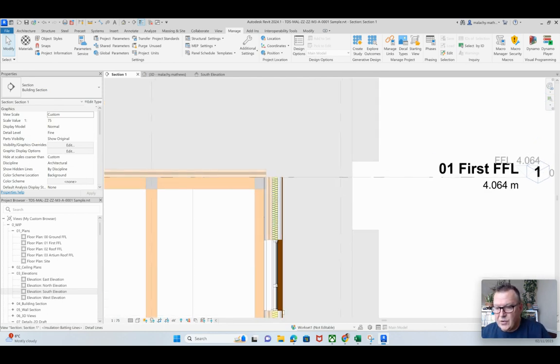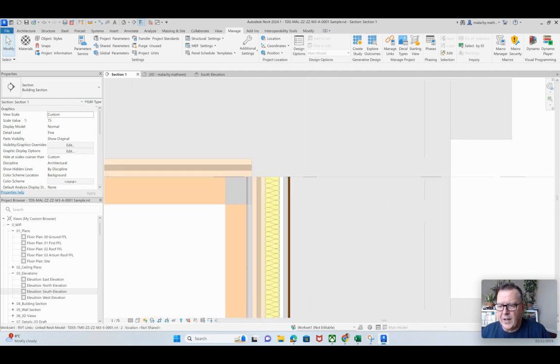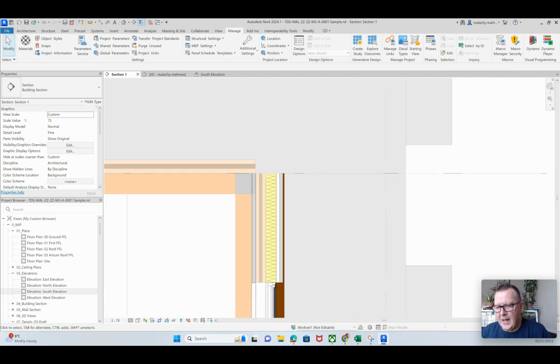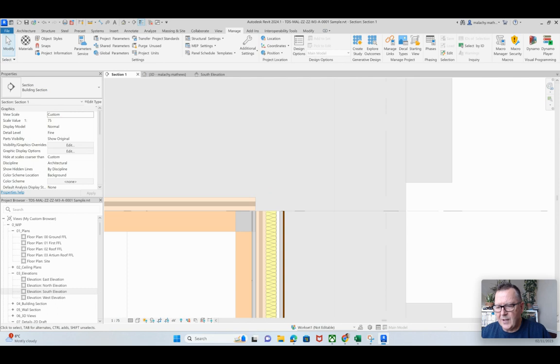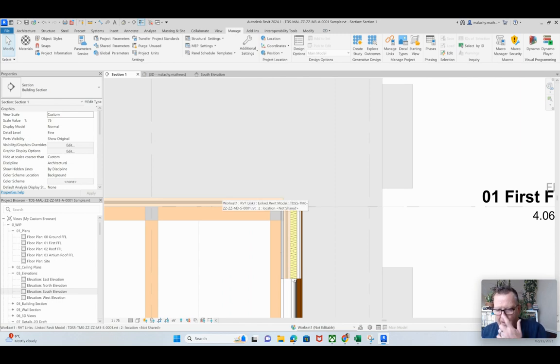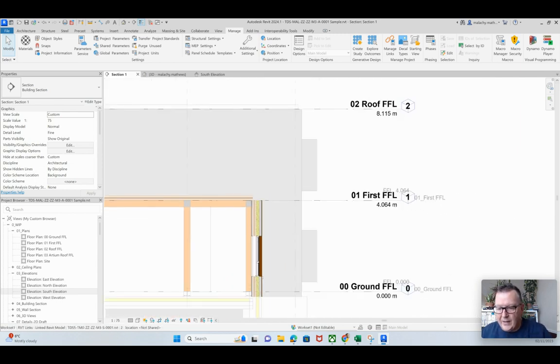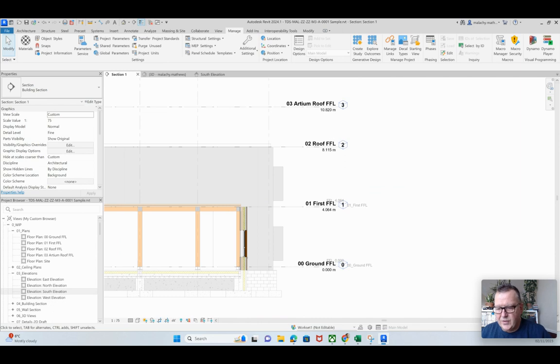And then here we get into the parapet. That's the way we're going to do that. So there's that CLT sitting on that beam. That's fine. That might allow me to take up this exterior wall up to around here or something like that. And then I will repeat maybe this detail on the inside, without the surface cavity, but I'd insulate that and maybe do a render or something like that, depending on what kind of finish I'm putting on the flat roof here as well. And I have to create a fall within that. All right, so that'll be part of the strategy there as well.